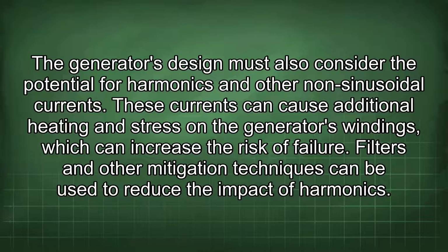The generator's design must also consider the potential for harmonics and other non-sinusoidal currents. These currents can cause additional heating and stress in the generator's windings, which can increase the risk of failure. Filters and other mitigation techniques can be used to reduce the impact of harmonics.